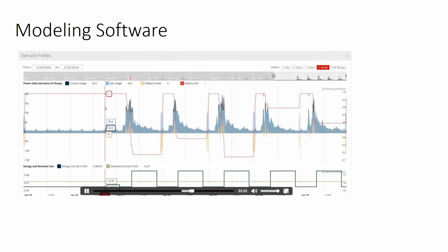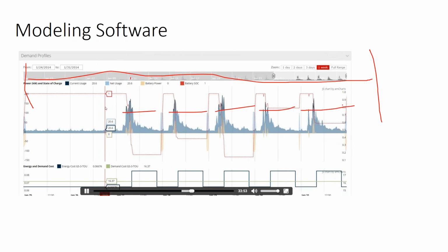And so what Energy Toolbase will do is take one year's worth of data of facility usage. It'll take your actual rate structure for inflow versus outflow, for demand versus energy, and it'll take your project installation budgets and run it through a financial optimization calculation to tell you what your optimal array size and optimal battery bank is.